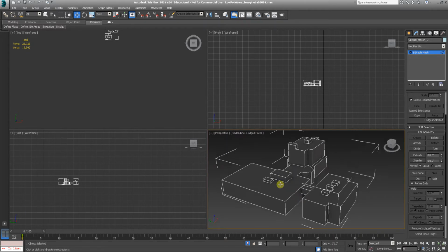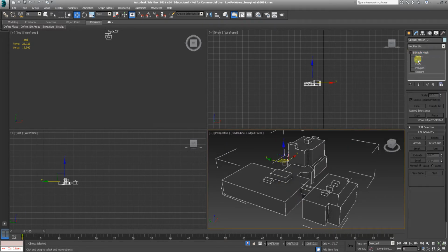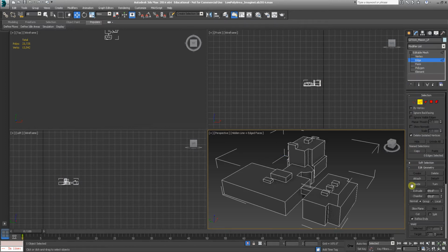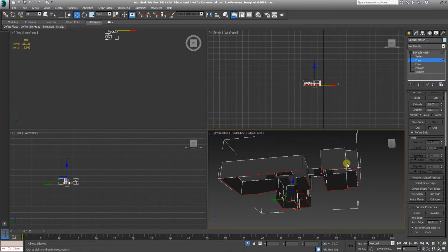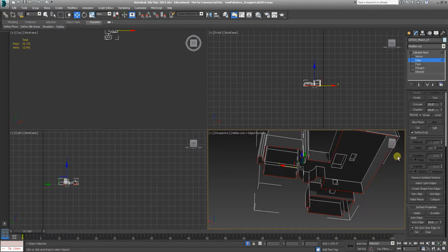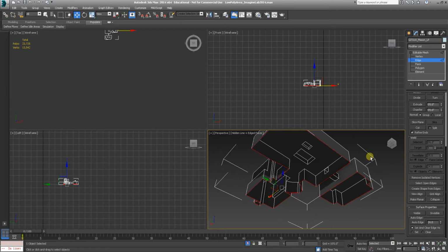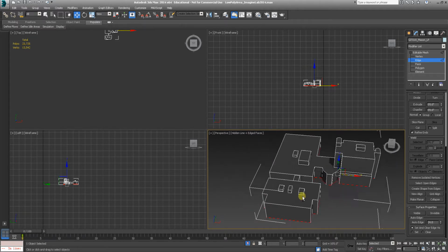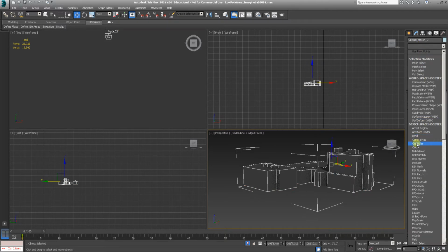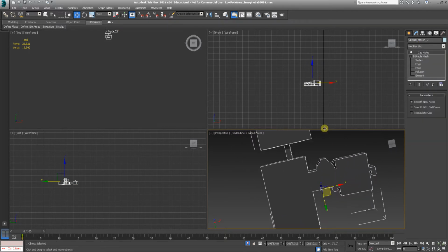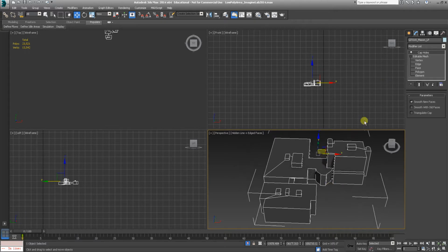So the first thing I want to do is figure out if I have any open edges in edge mode. So you got a couple ways you can get into edge mode, toggle in and out, and I can pan the window down and say select open edges. Now it's kind of like the naked edges in Rhino, and you can see I've got a pretty good set. It's that bottom set of open edges are the only ones I need to cap this thing. So I should be able to use the cap holes command, and that will usually do a good job of just capping it, and I should be ready to go. At that point, it does look like it did something funky there.